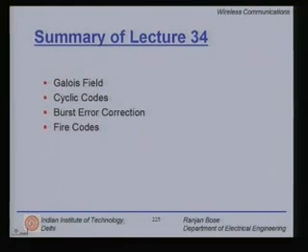We then briefly had a peek at the BCH codes, which form an important subclass of cyclic codes, not only because you can very easily encode and decode them, but also because you can have a constructive strategy for BCH codes. At this moment, please note that cyclic codes, BCH codes and Reed-Solomon codes, which is a subclass of BCH codes, though non-binary, are all linear block codes.